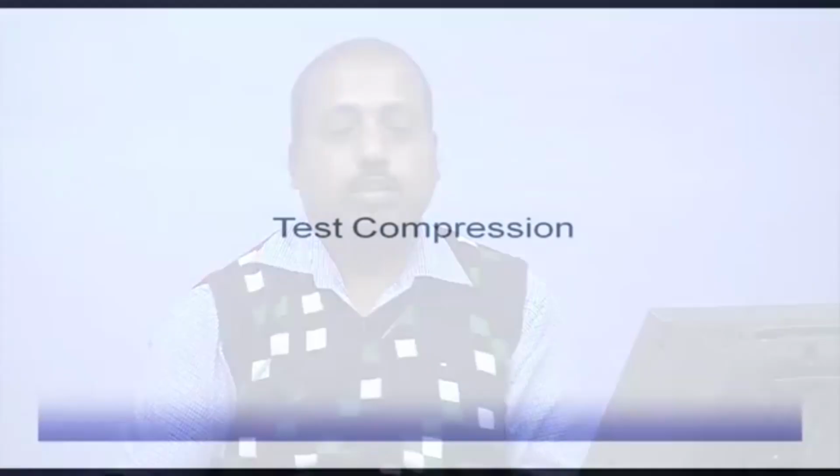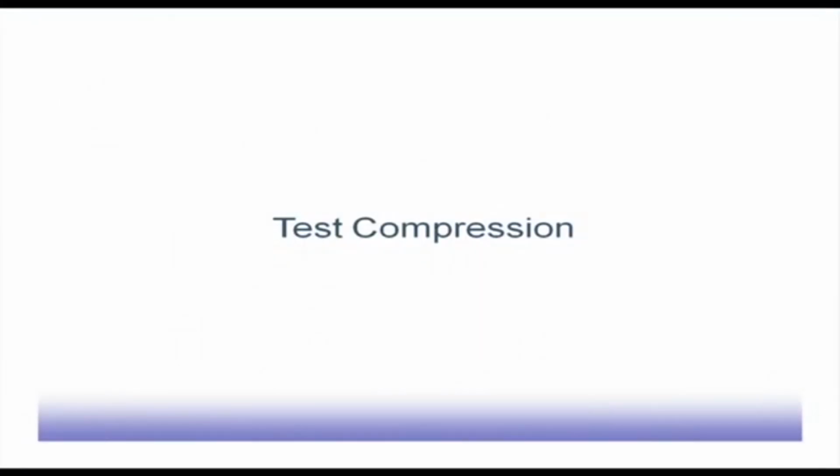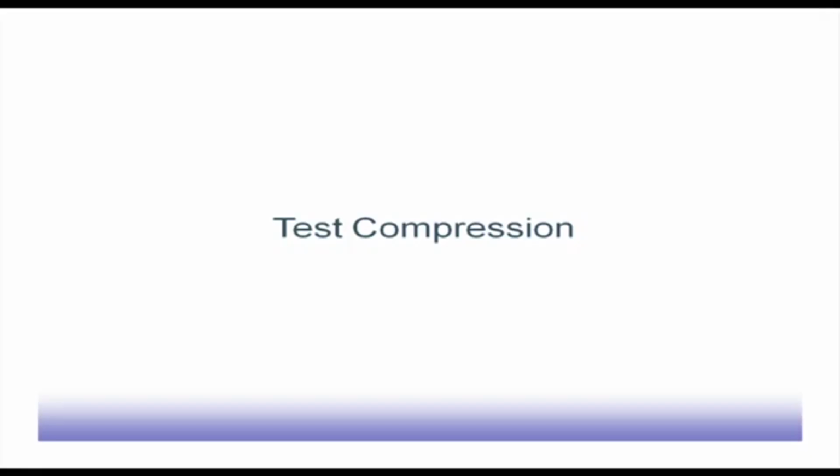Next we will look into another very important issue in testing, which is known as test compression. Basically, when we are storing the patterns in the automatic test equipment, we need to have a small number of patterns. But that is not always possible, because if we use a small number of patterns we will not get good coverage. So, we need to have a large number of patterns, but storing them becomes an issue. So, we want to store them in a compressed fashion.